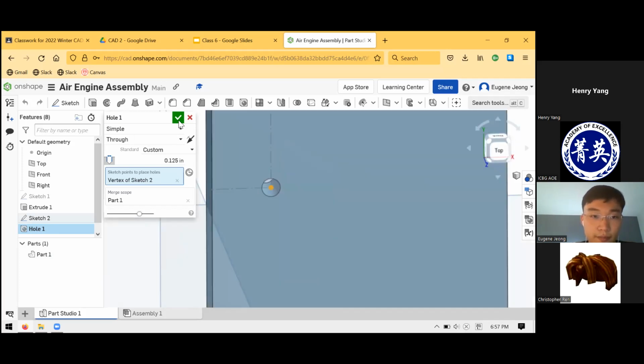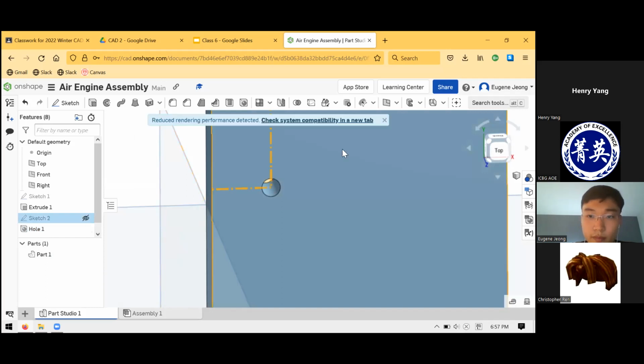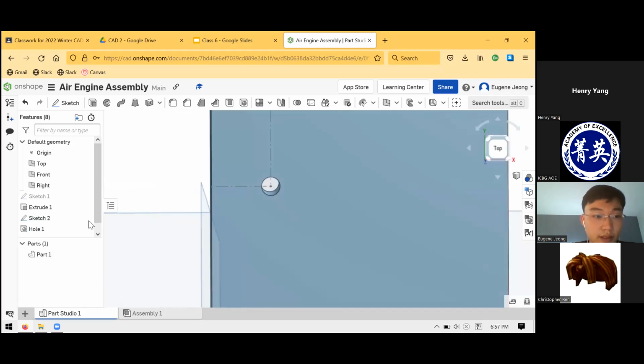Oh yeah, that reminds me of something. I had sort of a problem, but also not a problem on the crank wheel. Sure. So basically, in the recording, because I wasn't there, it said that I should use ANSI with thread and 32, but then that didn't work. And then I just tried. I just clicked on hole and then pressed the check mark, and it worked.